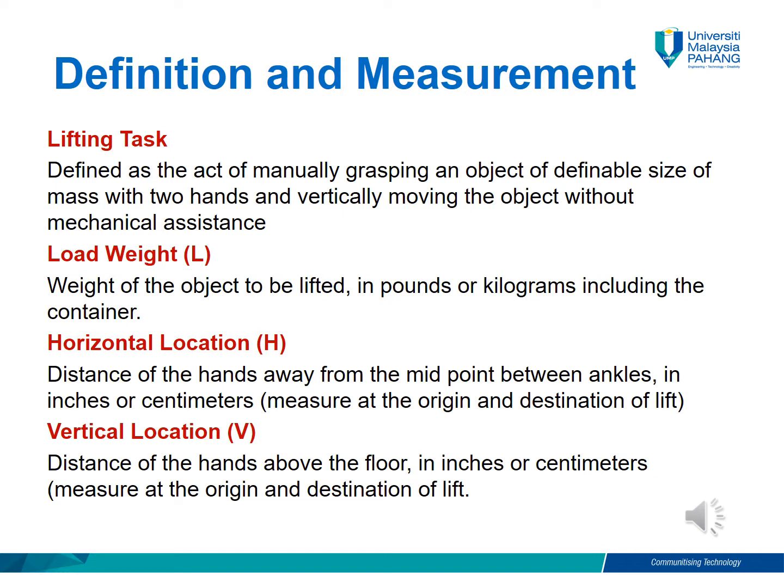So before you conduct the NIOSH lifting equation, you need to observe whether the lifting task complies with the definition. You need to know the weight of the object in kilograms, and make sure that you can only move the object vertically, without mechanical assistance, without a hoist or conveyor or whatsoever.